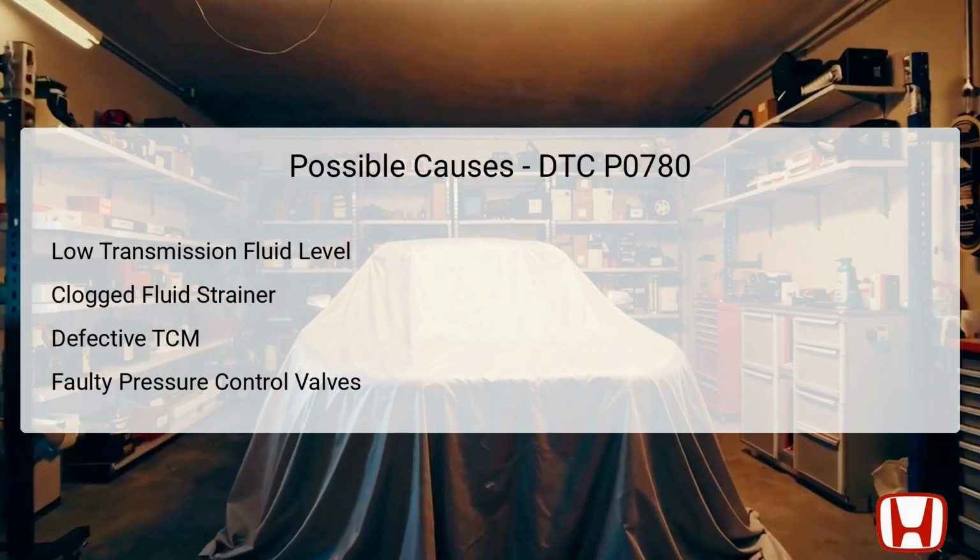Furthermore, faults in the CVT drive pulley pressure control valve or the driven pulley pressure control valve can disrupt fluid dynamics, which are essential for proper gear shifts. Addressing these potential causes is critical for resolving the DTC and restoring normal transmission functionality.